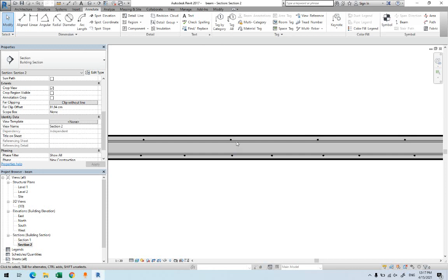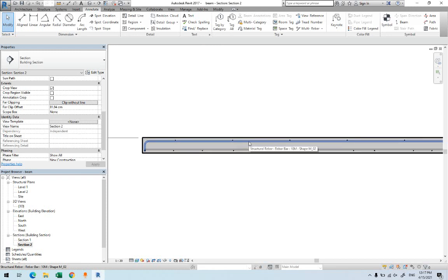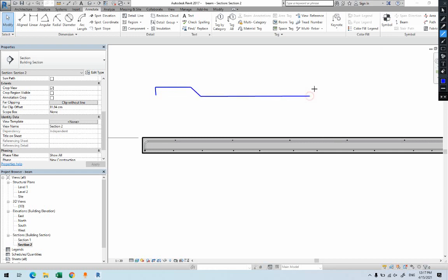You could provide additional, let's say if you don't like the straight at the top, you can remove them and you can add additional. Remember we said there is a different way that we'll provide. Sometimes we have one bent up, and I said this is the bent up going. We don't have straight at the top. We have straight at the bottom, but we don't have at the top. So in that case, you don't need the top layer. You just have to put additional bars here, which you can sketch by yourself easily, just somewhere here. No need to put the top bar here.